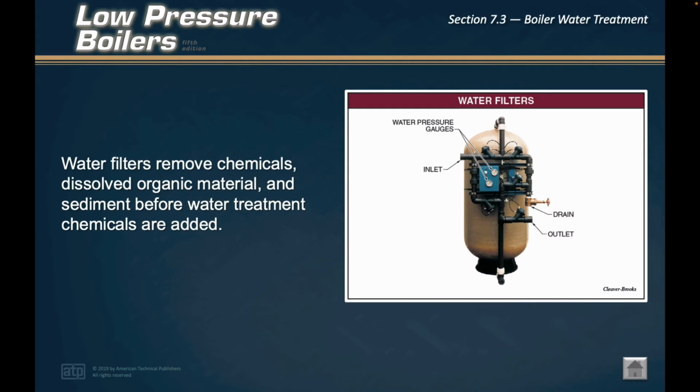External boiler water treatment is treating water, or feed water, before it enters the boiler. Oxygen and non-condensable gases can be removed by heating the feed water. The gases are then vented to the atmosphere. Heating the feed water also reduces thermal shock from water fed to the boiler. Feed water treated before entering a boiler contains all or most of the scale-forming minerals causing water hardness.